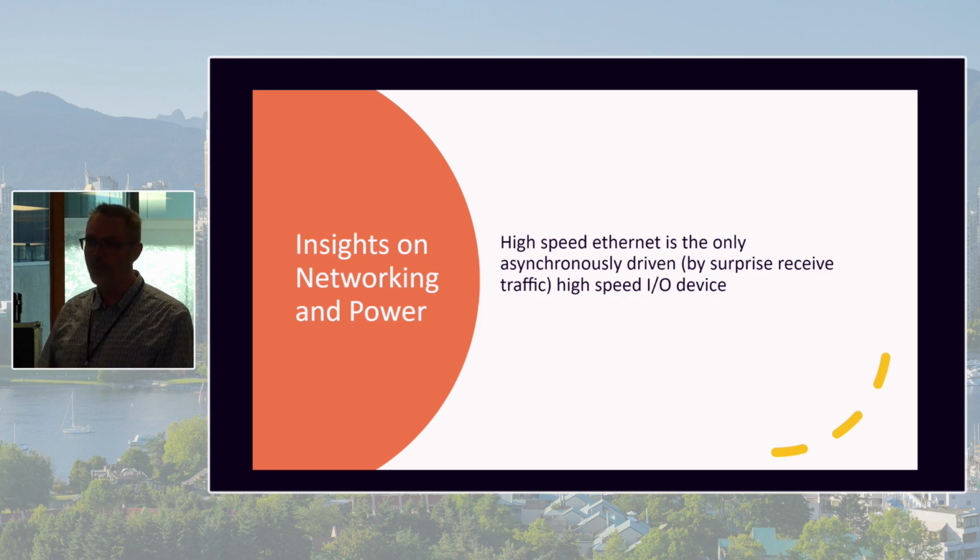So you have this surprise I/O, and everything is having to wake up, possibly from package C6, which might take hundreds of microseconds to wake out of, right? Which would really suck.